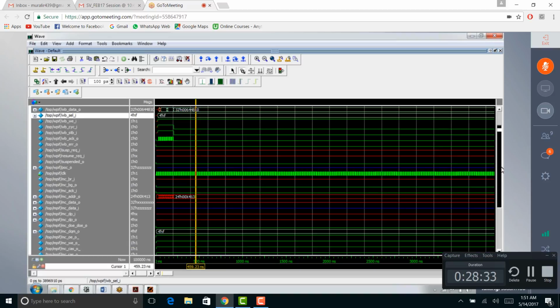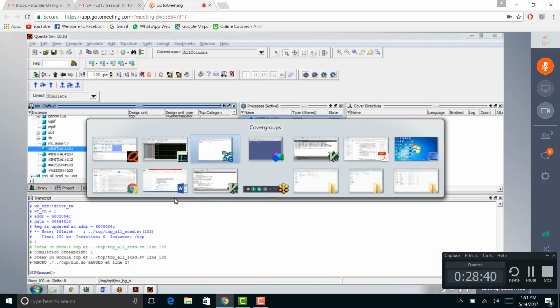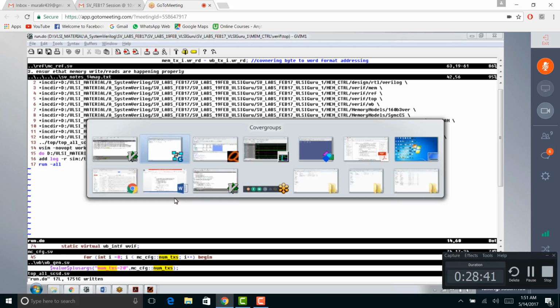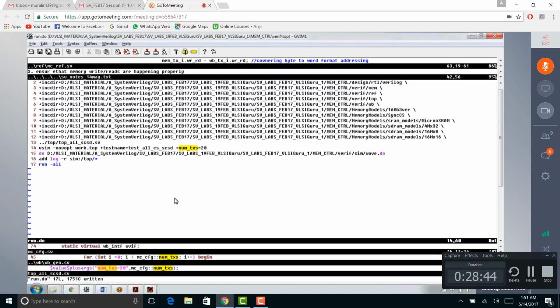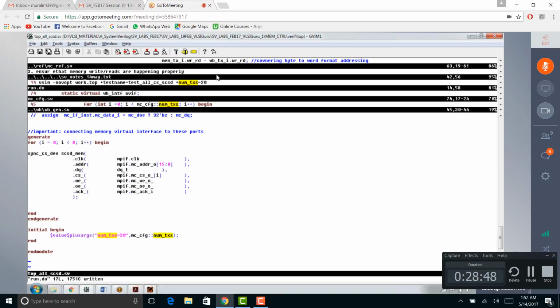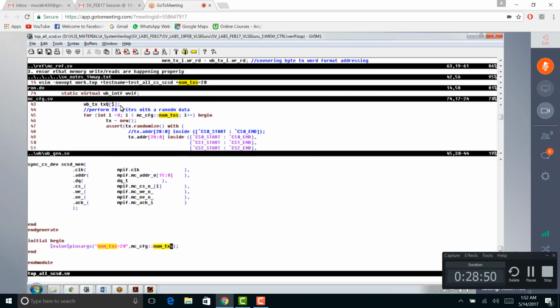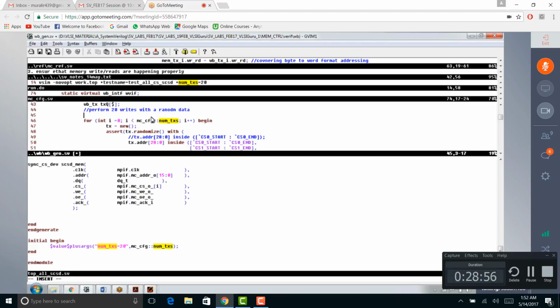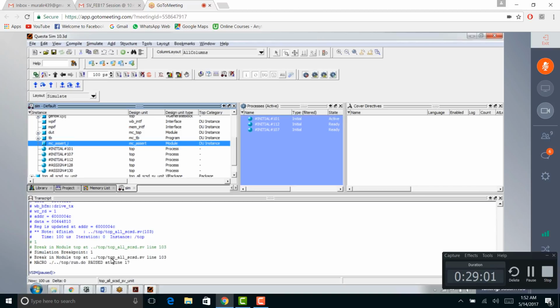They are not happening, right? Something has gone wrong. That is because, I'll tell you what happened, it is called a race condition. By the time you passed it, by the time it read, it had already started this flow. That is where it is going wrong. Rather, if I give a #0 delay, it will work.